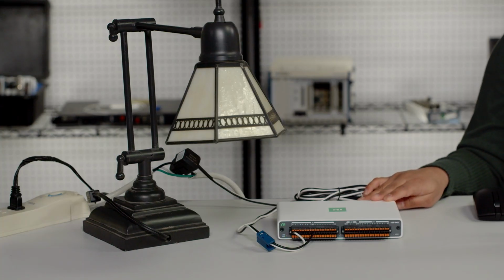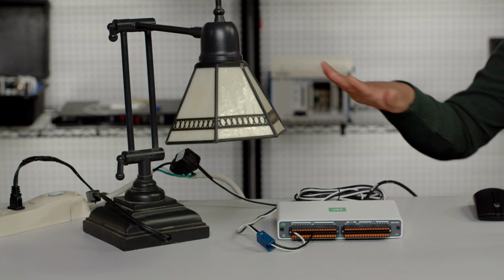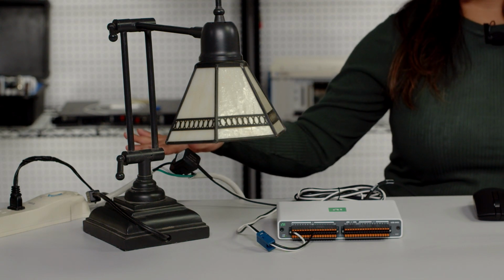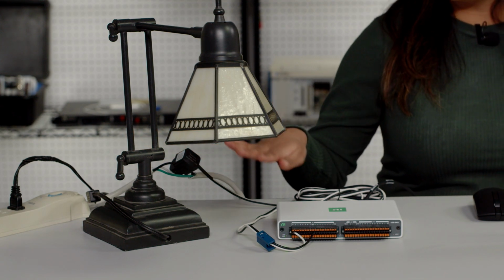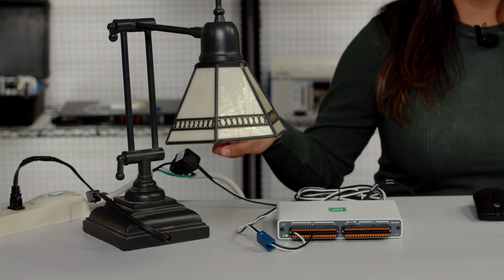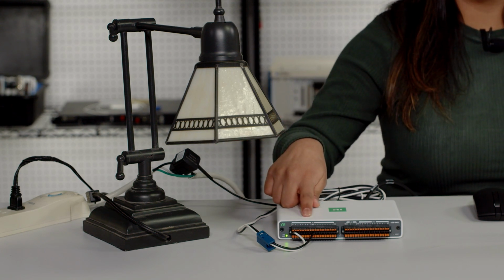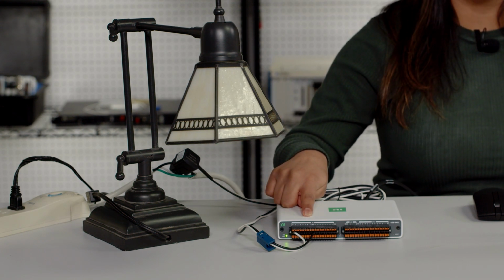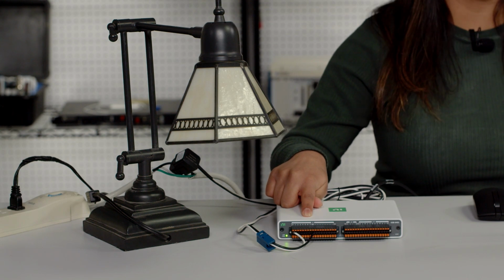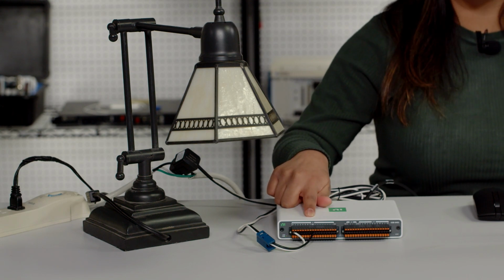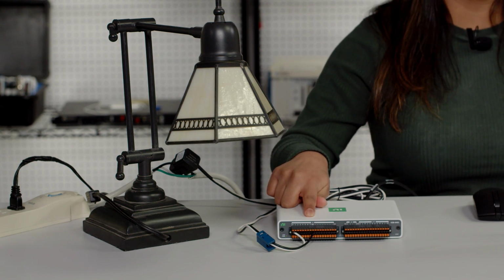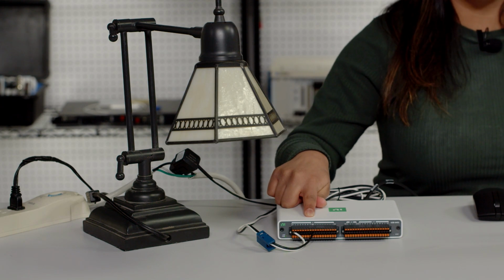So in front of me, I have FlexLogger already opened on my screen, and I've already connected my mioDAQ device using a USB cable. Now we also have a lamp, which we've plugged into our outlet, and we're using a CT to measure the current coming out of that cable. And that is connected to our mioDAQ device. So the white cable is connected to AI0, and we have the black wire connected to ground, which means that we can use a referenced single-ended configuration.